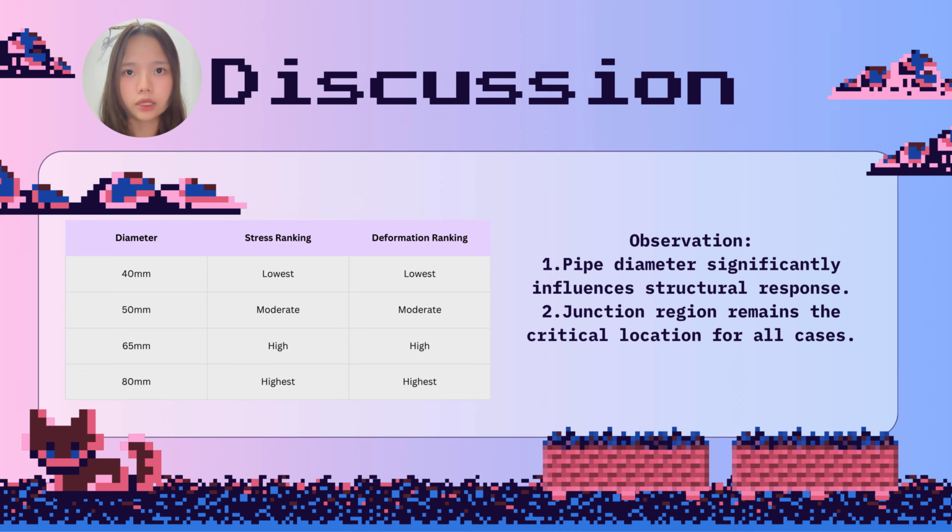Overall, the results clearly showed that pipe diameter has a significant influence on the structural response of the branch pipe junction. In all cases, the 40 mm pipe produces the lowest stress and deformation, while the 80 mm pipe produces the highest values. In addition, the FEA analysis identified the junction region as the critical region for all pipe diameters.